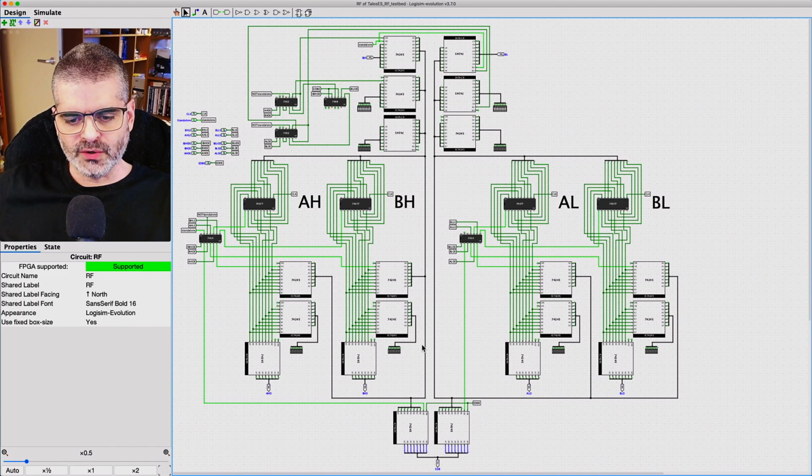And you see the four LED bars here, here, and here, driven by its own dedicated buffer, so we don't have overcurrent coming out of any IC pin. This is just to visualize the contents of each register on the respective LED bar. That's all there is to it. There is no computational functionality here, it's just to visualize.